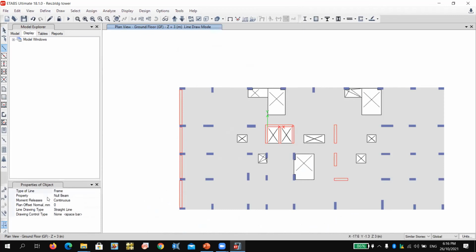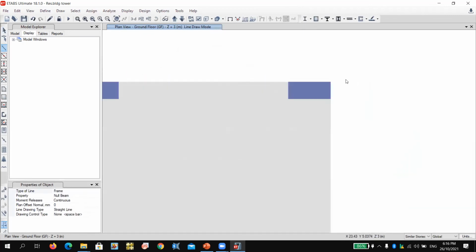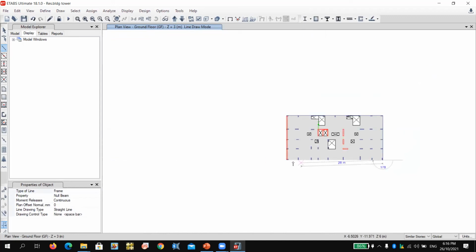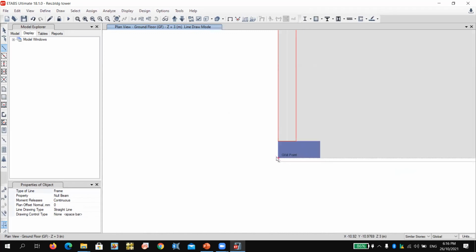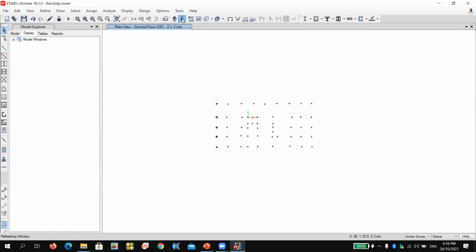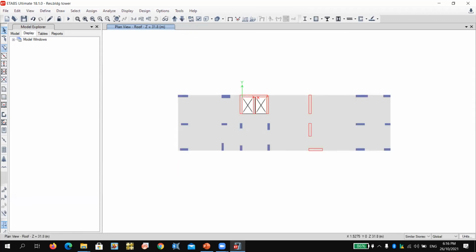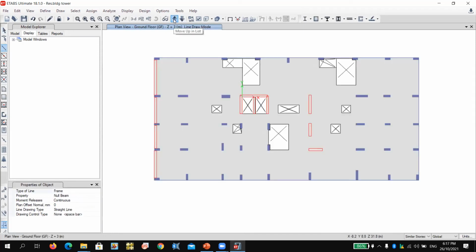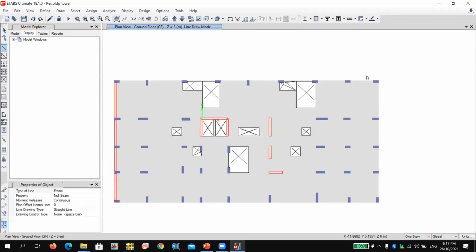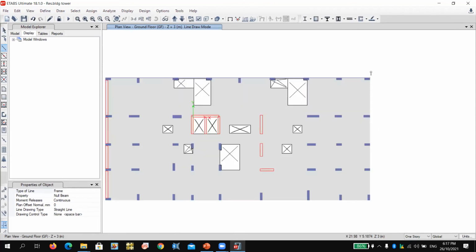So now we draw the null beam again, starting from this point to this point, downward to this point, and continuously reaching from this side. It's not necessary because we have it. So this is the beam, and we still have the rooftop. The rooftop also has it. I made a mistake here. Remove this, undo. It should be only on the one story. So be careful again. Null, go to this joint and continue to the end of this joint.